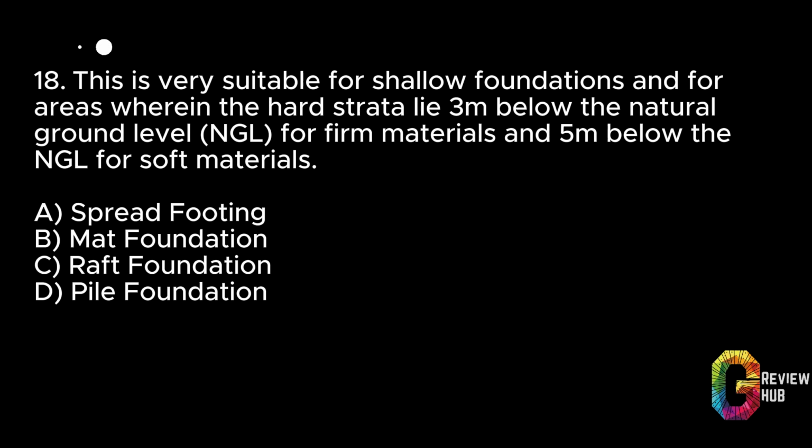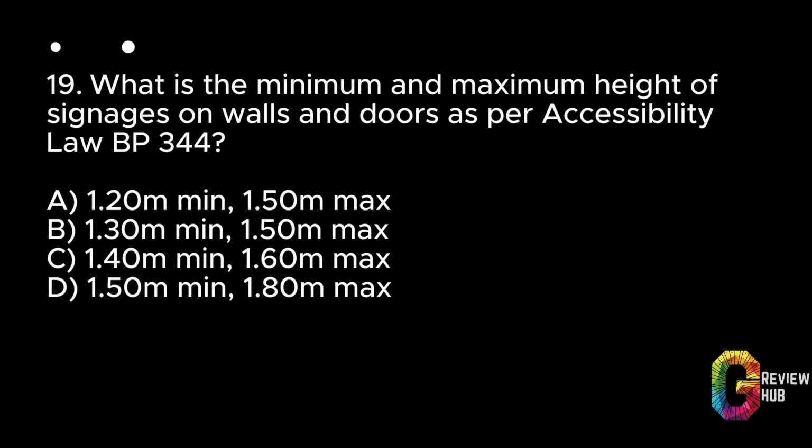18. This is very suitable for shallow foundations and for areas wherein the hard strata lie 3 m below the natural ground level, NGL, for firm materials and 5 m below the NGL for soft materials. A. Spread footing. B. Mat foundation. C. Raft foundation. D. Pile foundation. Answer: A. Spread footing.